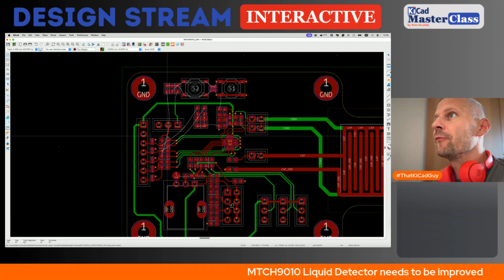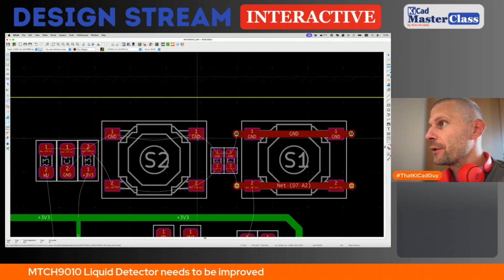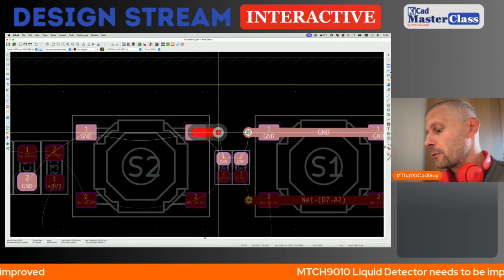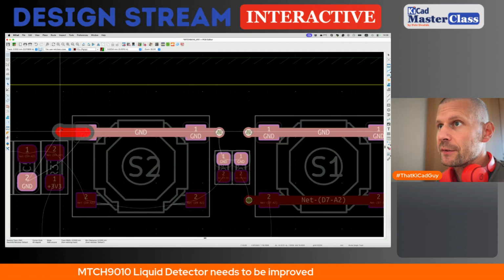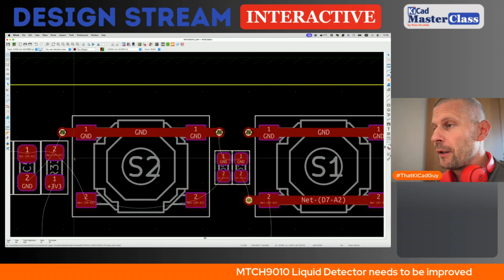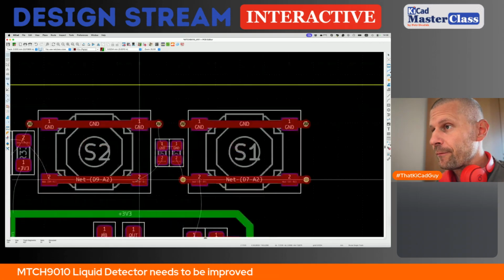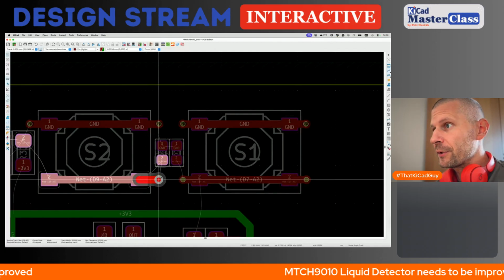Okay, so let's work on the layout. We can start with the button, in a similar way as before. I will place these two vias connected to only one layer. The reason is to provide the PCB with some firmness, to be resistant to damage on the buttons.